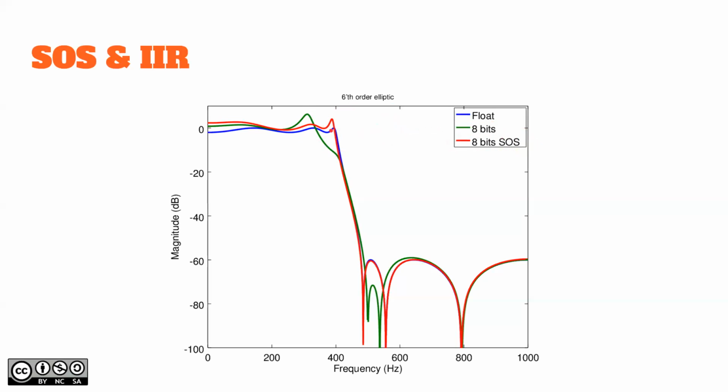So it's a couple of dB higher, but well, that's the easiest possible thing to fix on any system. Even with 8-bit arithmetic, you can multiply it with a bigger number and then divide it with another number, and that's how you gain this gain.